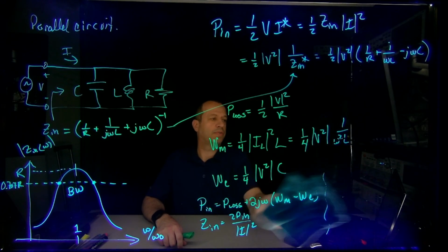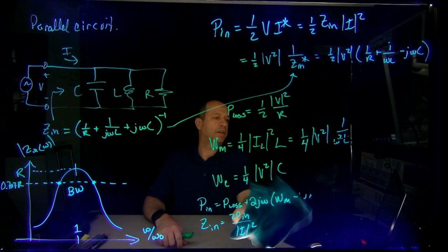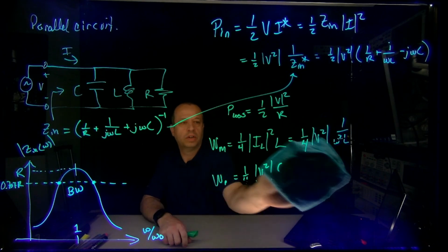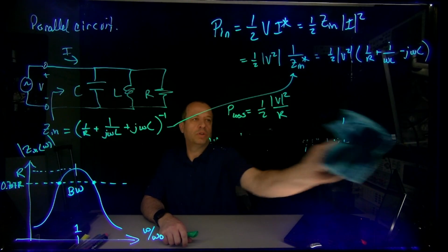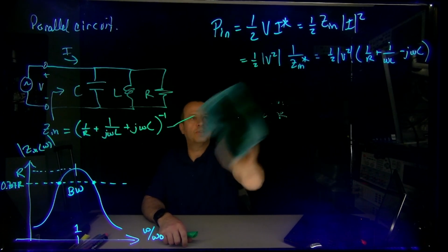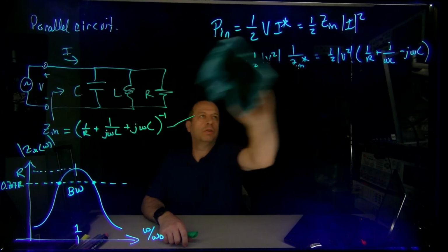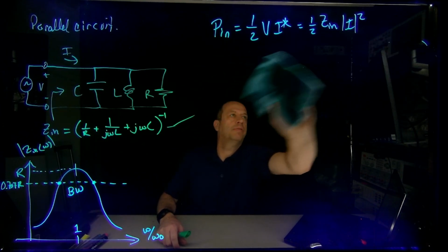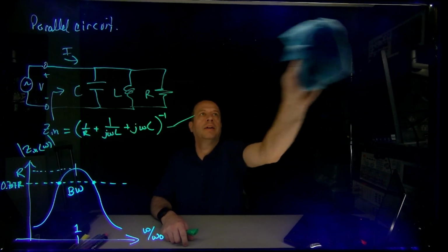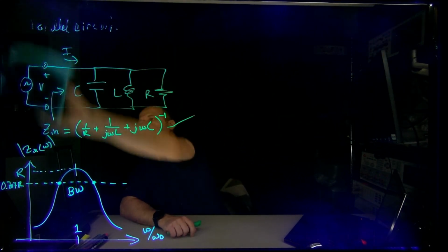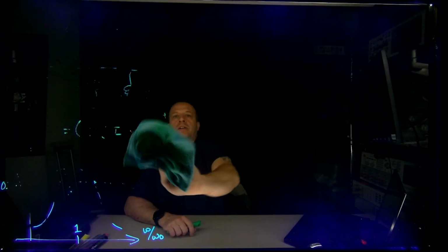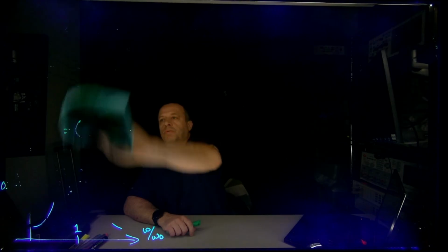Probably one of the more frustrating things about microwave engineering is that anything you do to this circuit affects all of the circuit. So putting a trace on your board in a random location or routing from one side to the other that gets a little close to anything, microwave signal strength can affect everything else on that line. And by the act of you trying to fix that, rerouting the trace, running it somewhere else, can affect other parts of your microwave design.